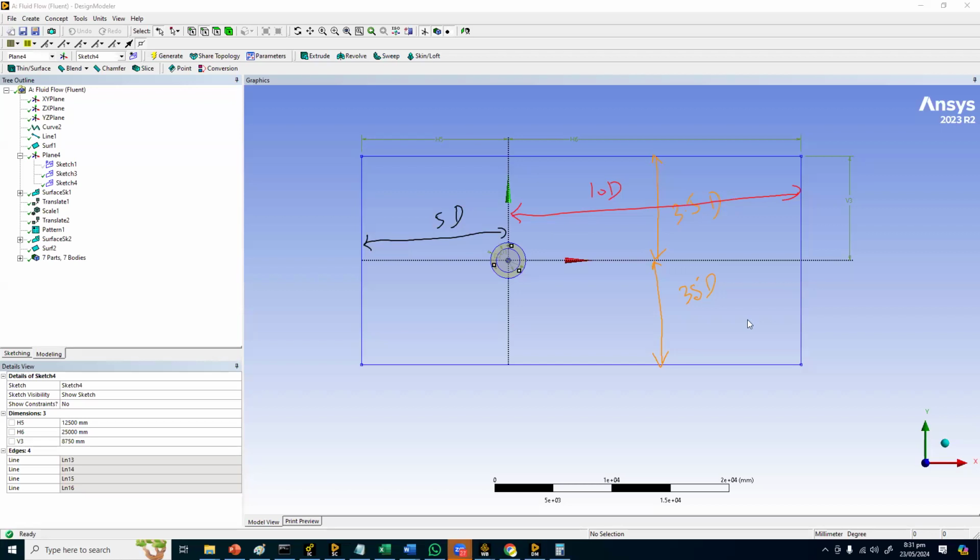The purpose of the upper domain is that the wind turbine is operating in some atmosphere. It is actually working in some atmosphere where we have wind. So we are modeling some portion of the wind that is part of that particular region, so we can get the boundary conditions or the flow from those local conditions. This is a control volume that will encompass the wind turbine plus some portion of our atmosphere.